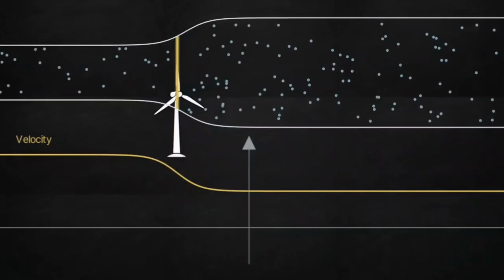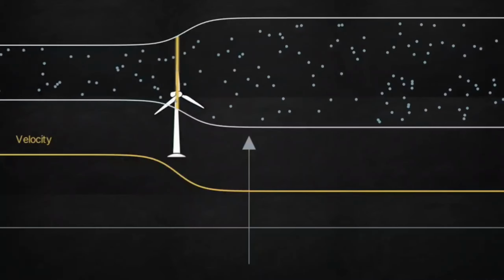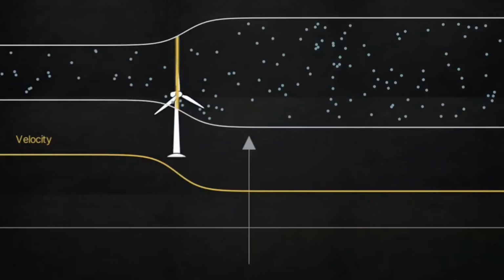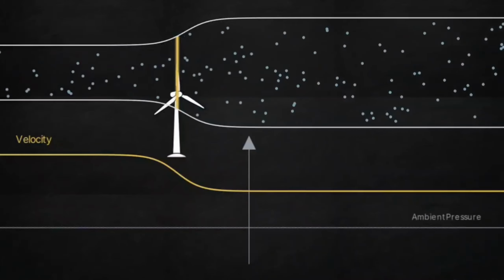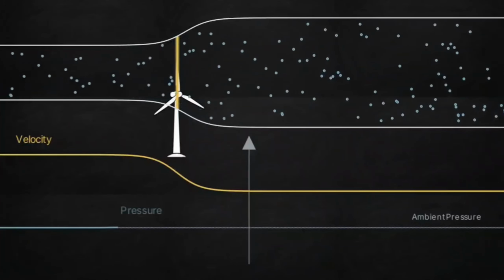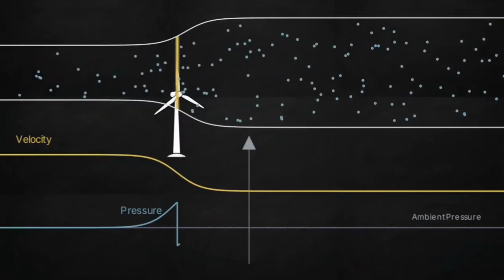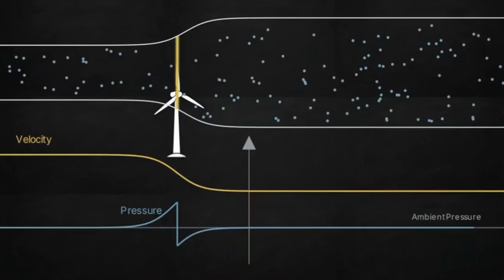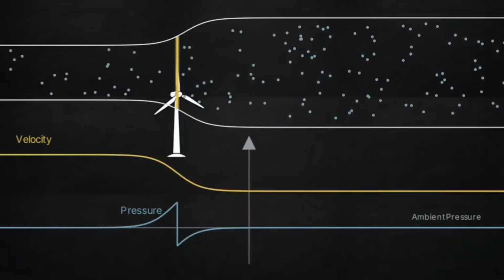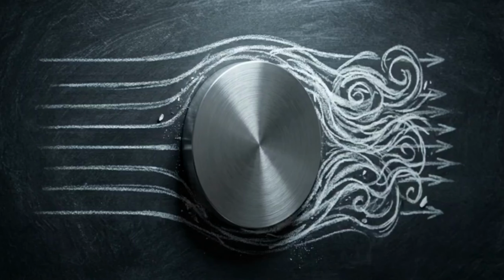As the disk extracts kinetic energy, it physically slows the wind velocity. To maintain equal mass flow, the slower downstream air has to spread out, causing the stream tube to expand. A second graph overlays the inverse effect on pressure. As air hits the rotor plane, pressure spikes up, then instantly plunges below ambient levels on the other side, before gradually recovering. Attempting to extract 100% of that kinetic energy creates a physical paradox.